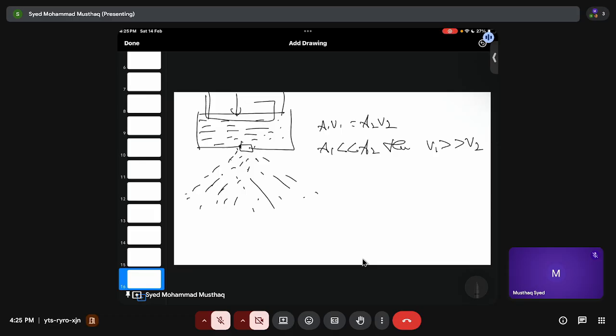And a very interesting part about atomization is that this is a process by which you form glasses of metals, right? We know from metallurgy, whenever you cool a metal pool very fast, like 10 to the power of 3 to 10 to the power of 4 Kelvin per second, or 10 to the power of 5 Kelvin per second, then you will form metallic glass. And to cool it very fast, you need to have as large a surface area as possible, which can be attained by very small droplets, and that is done again by atomization.